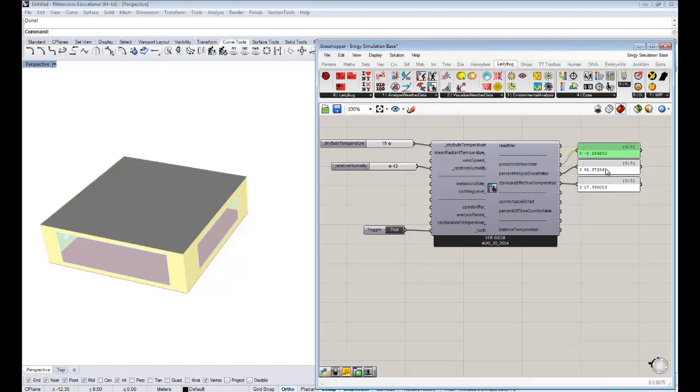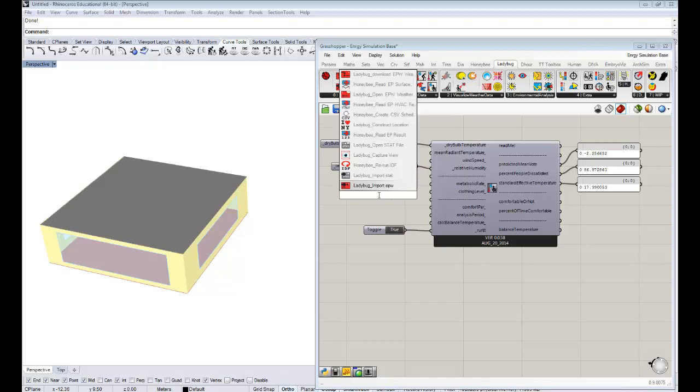I mean, 86% of the people say they're unhappy. But you can start to make an argument: I actually know that people in this place are willing to wear enough clothing that might make these conditions comfortable. So you can make a slider that goes from, say, socially acceptable levels of clothing, which are about 0.4.